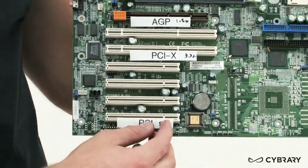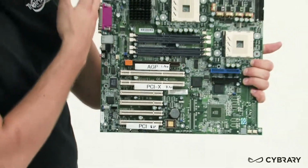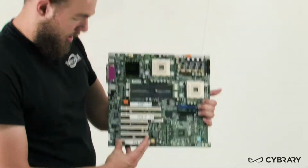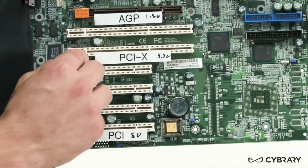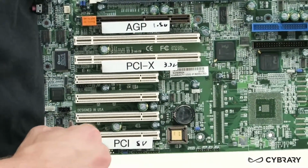Now, when I say left and right, this is looking at the board with our input-output to our left side. And that's how we can tell the left from the right on our card here. The next PCI slot that we want to look at is our PCI-X slot. PCI-X is actually a 64-bit slot, whereas our PCI was only a standard 32-bit.